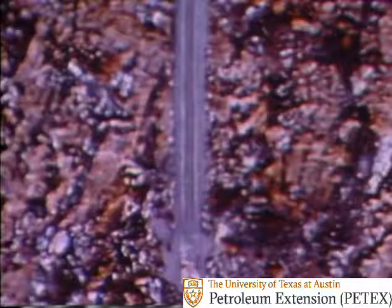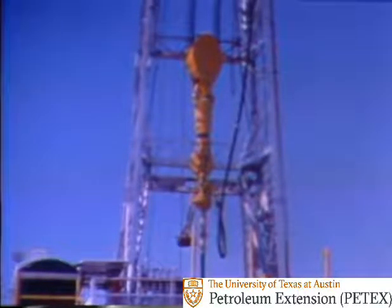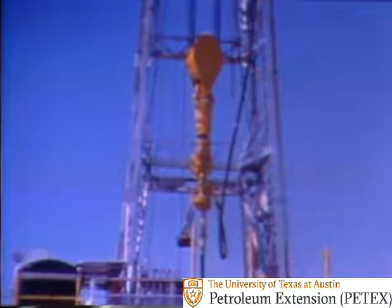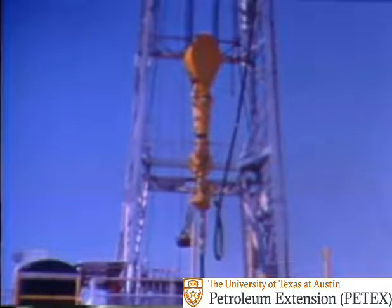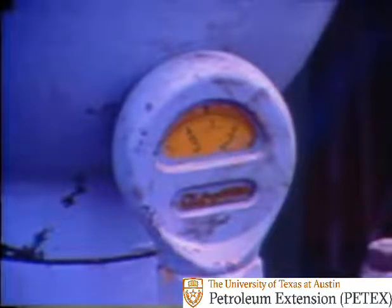These friction losses vary with the viscosity and gel strength of the mud, the length and diameter of the surface piping, diameter of the drill pipe and drill collars, the size of the bit nozzles, and clearance between the drill stem and wall of the hole.